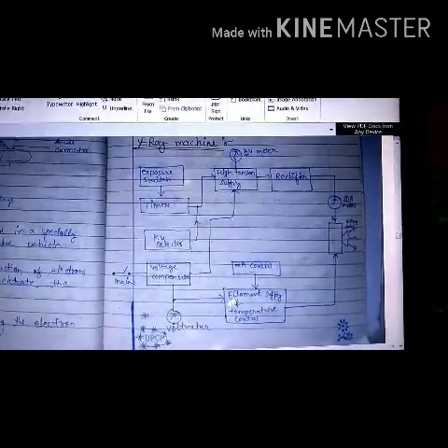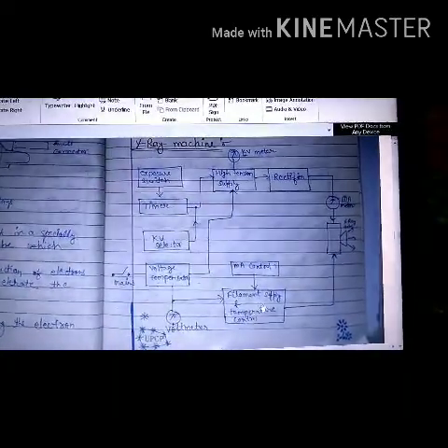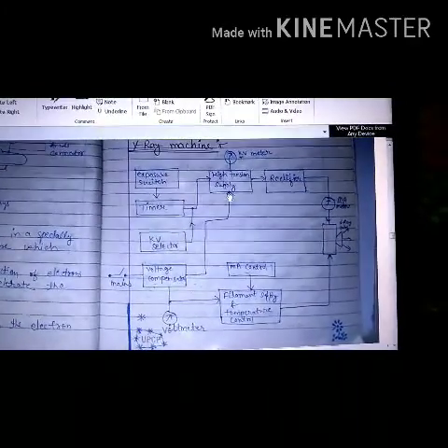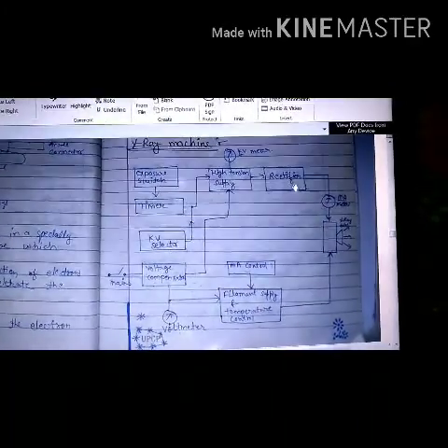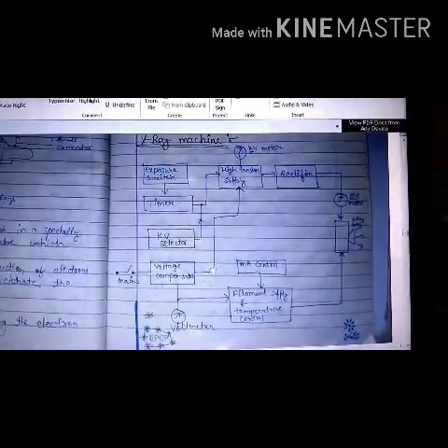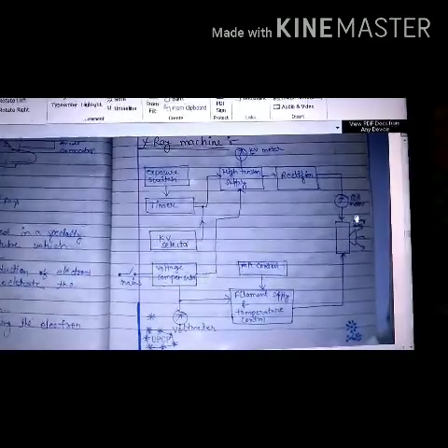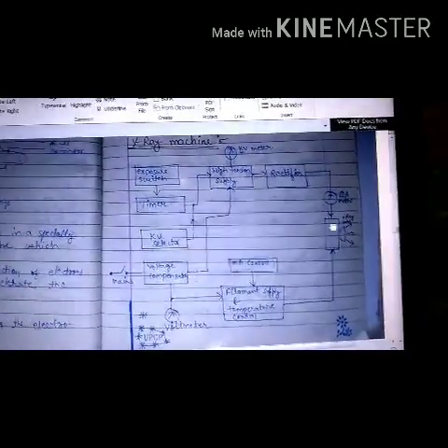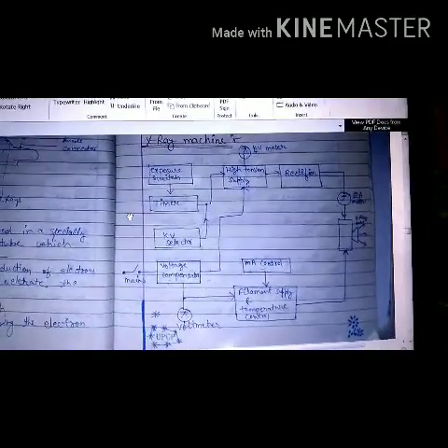Then there is a filament supply and temperature control switch with a milliampere control. Then there is a high tension supply and a rectifier, which converts the AC current we get at home to DC milliampere current. And this is the complete setup, with the X-ray tube where the X-rays are generated.